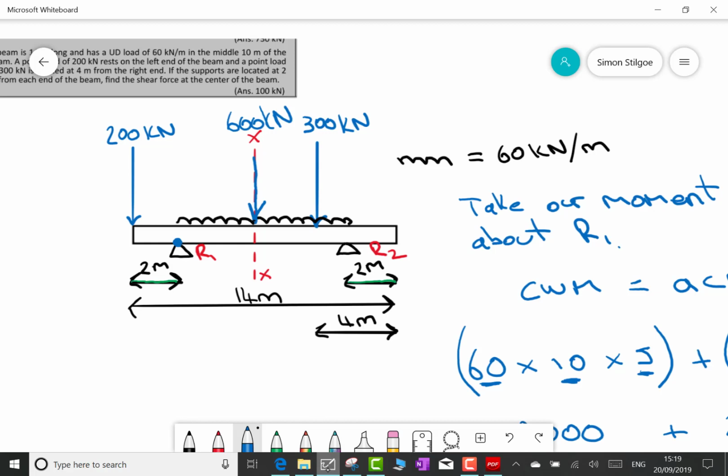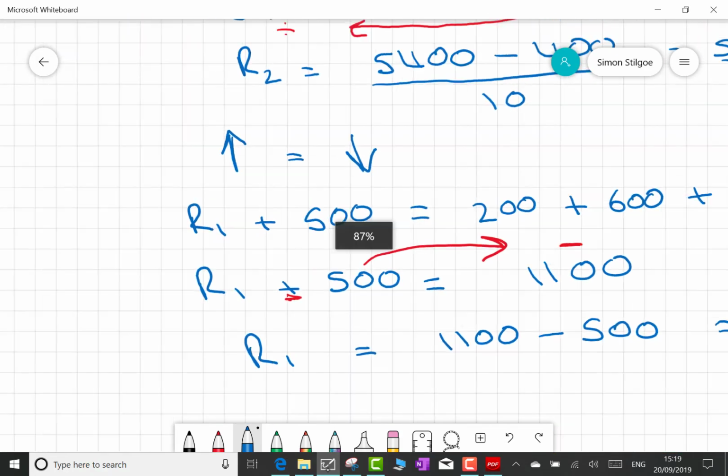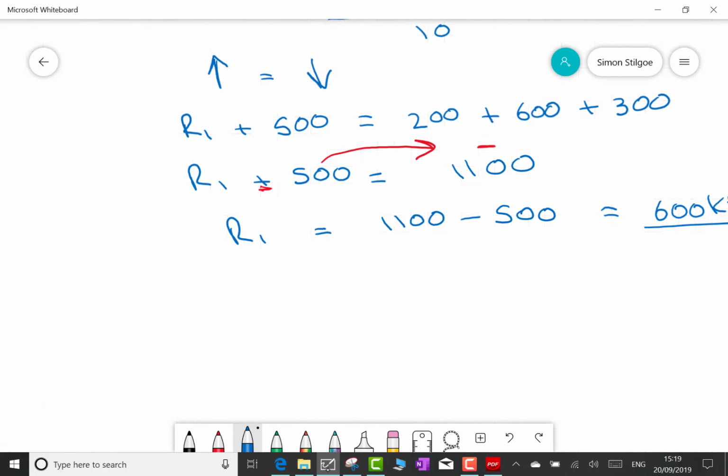As I said earlier, it doesn't really make a difference if you go left or right with this one because the shear force is in the center. But to keep it consistent, we'll go shear force to the right. So let's do that. Let's just zoom out here. So shear force going to the right hand side. Now remembering, downwards forces are negative and upwards forces are positive.